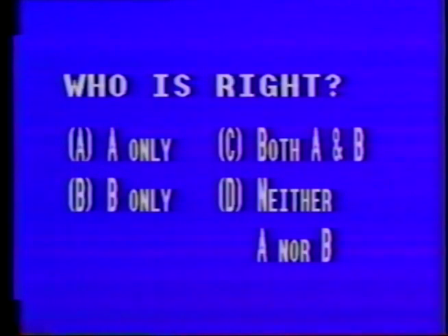Technician A says slow flashing turn signals can be caused by the wrong type of flasher. Technician B says slow flashing turn signals can be caused by bulbs of incorrect wattages. Who's right? A only, B only, C, both A and B, D, neither A nor B.